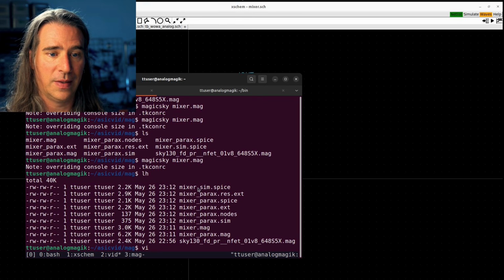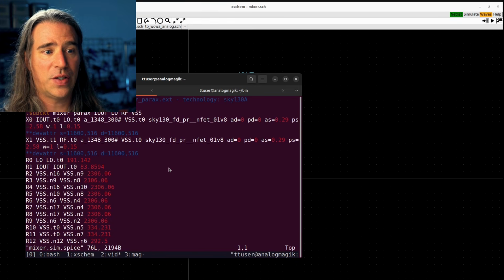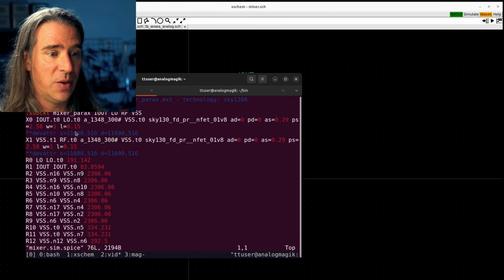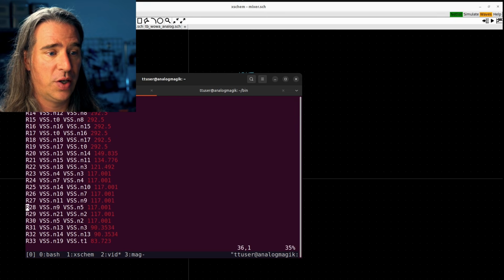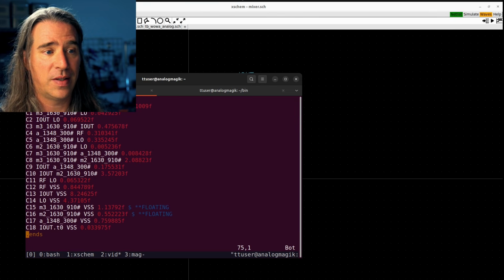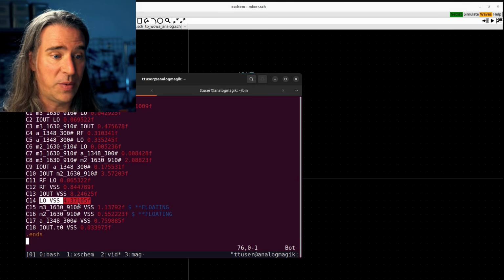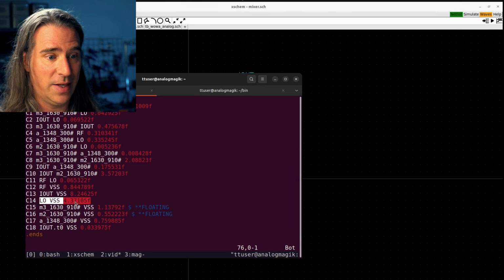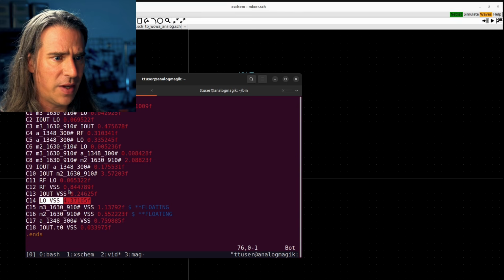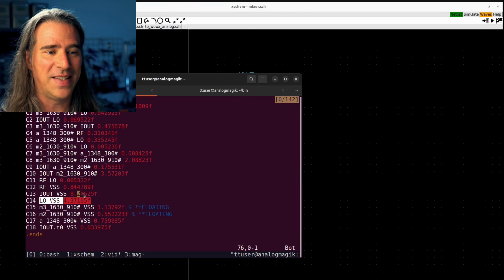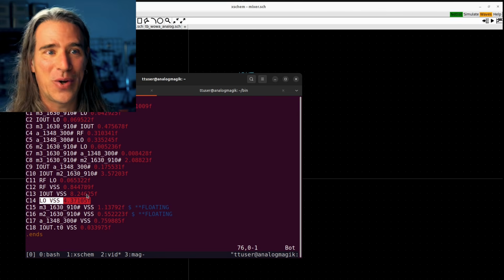Look at this. Instead of just our two MOSFETs, we've got a bunch of junk. And so all this parasitic resistance, and importantly, these caps here. So between LO and VSS, suddenly we have 4 femtofarads, which isn't a lot, but here is a lot. And we should have another one. Where was it? I out and VSS. Oh, yeah. Oof. 8. Okay, so let's try that out.